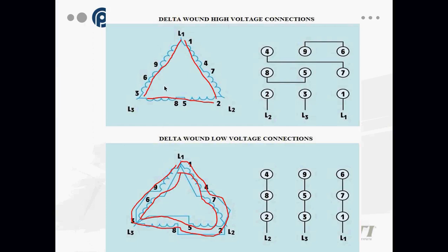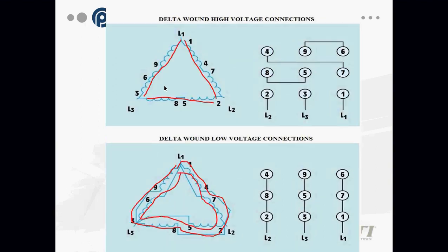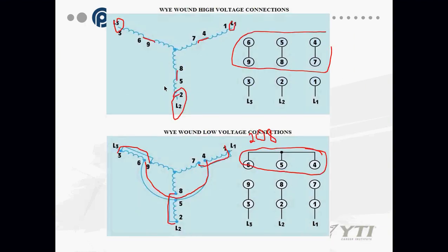These motors are neat because you can actually have one motor with two voltage configurations. Guys, these two slides, I would really recommend that you download the handouts or the PowerPoint and save them. I took an electrical certification test a few years ago, and I had a hard time finding these. They're on the motor labels and in the handouts that come with motors a lot of times, but over time those things get lost. Once you know what you're looking at, you can use an ohm meter and find the different windings, find the different pins.